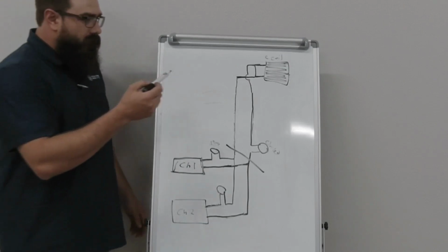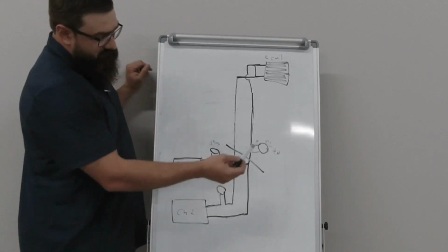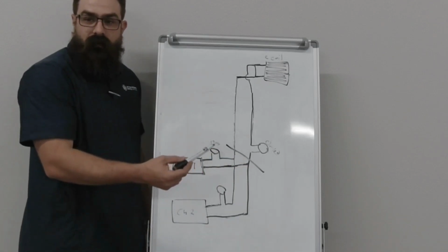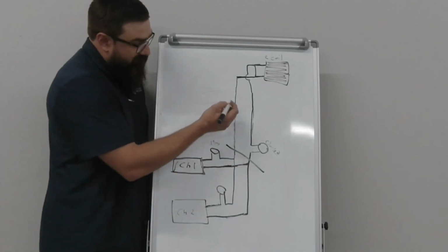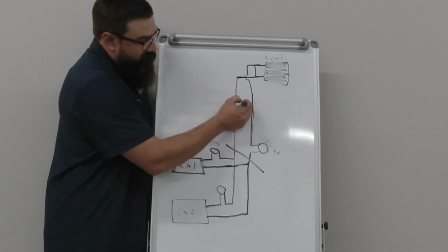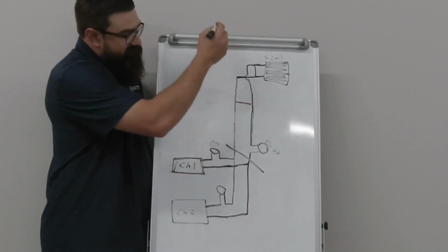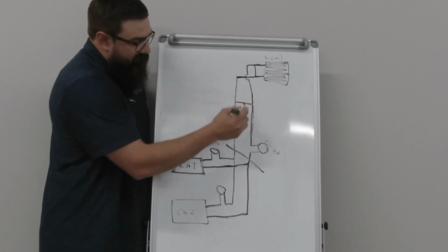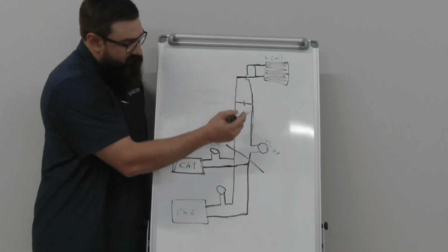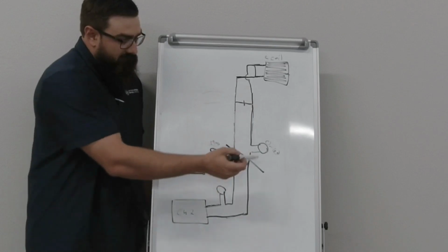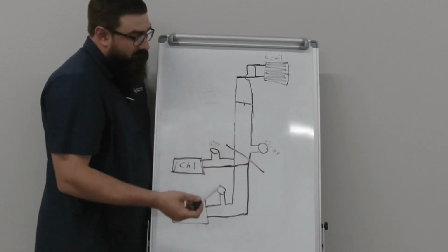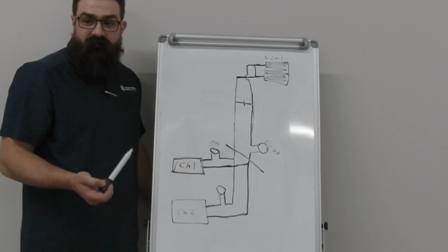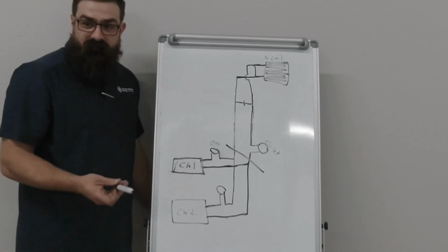So that allows us to, in some systems, run a pump at 100% all the time. And then what we would do is we actually have another valve either way up at the top or down in the plant called a bypass valve. And what that valve can do is it can open and close based on that pressure. It can be on a constant volume system, or it can be on a variable volume system. So some pumps modulate, some pumps don't.